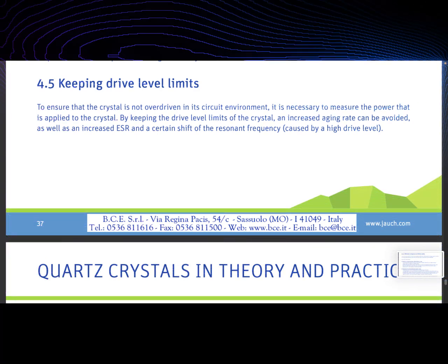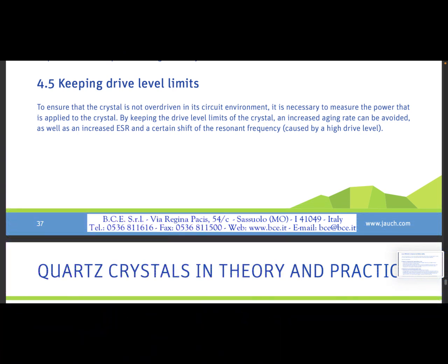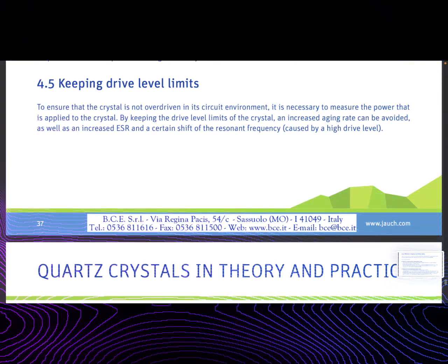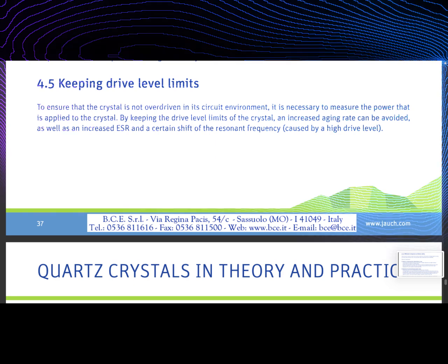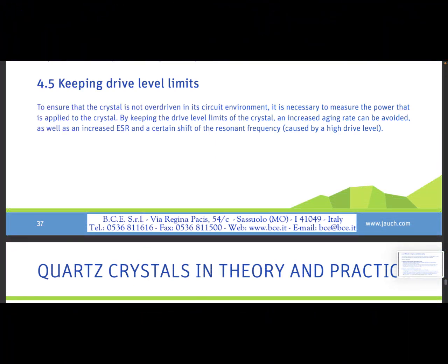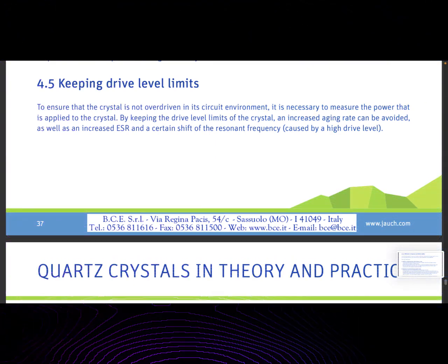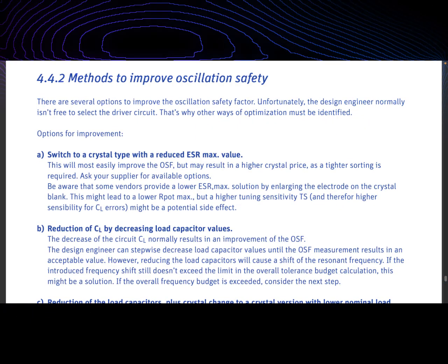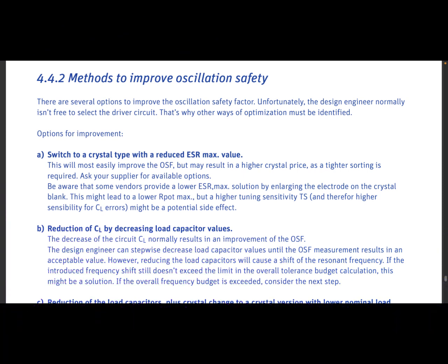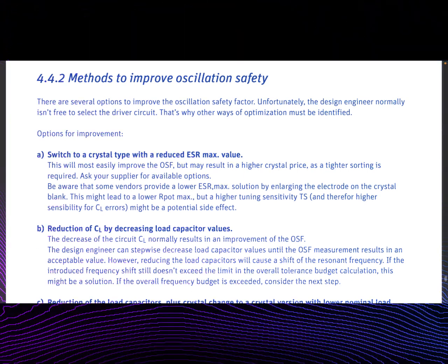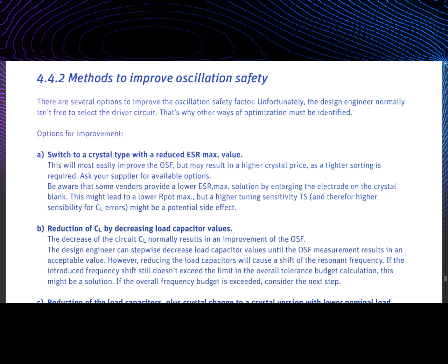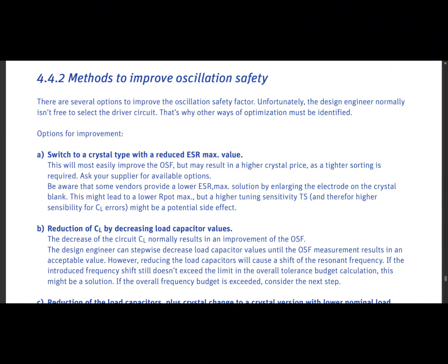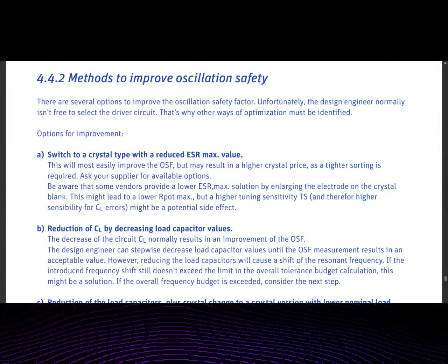Due to this property, crystals that make use of the AT cut angle are very suitable for applications requiring a high degree of frequency stability over a wide range of temperatures. In addition, the AT cut angle ensures low aging and a high quality factor Q.